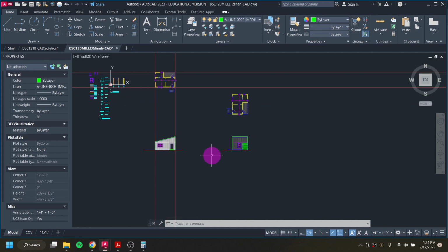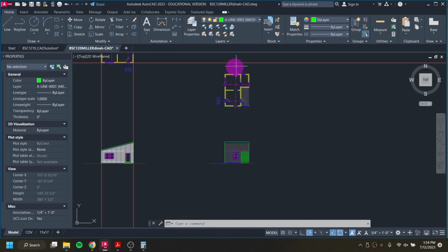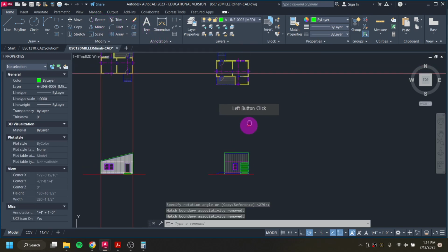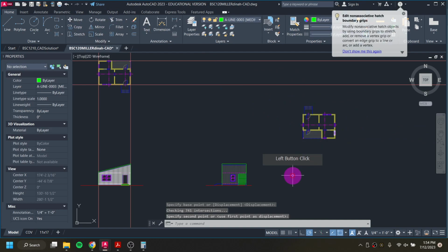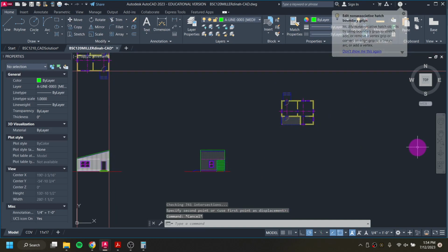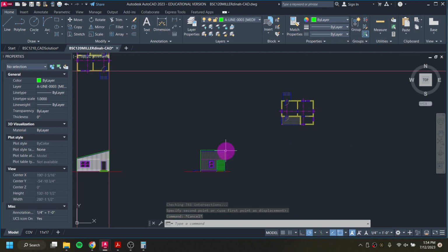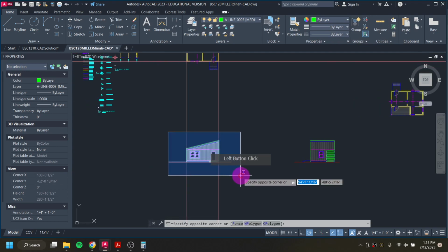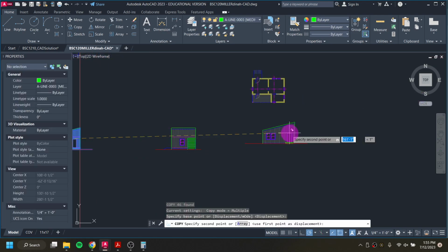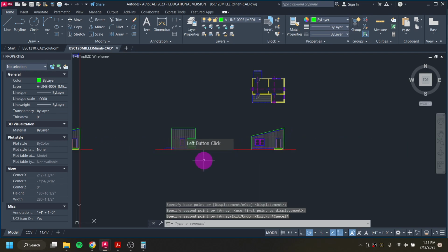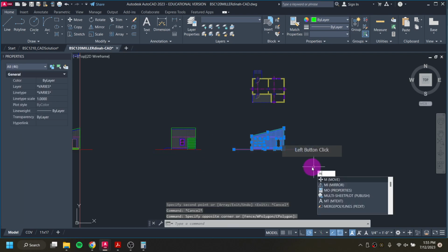If you wanted to do the north and the west elevations for extra credit, you can absolutely use, especially for this method that we use for the east one, where we could take this copy and rotate it this way, move it so that it was sitting over here, and then use raise and our tools to also bring over our heights. You can also make a copy of the south elevation and then highlight it and mirror it.